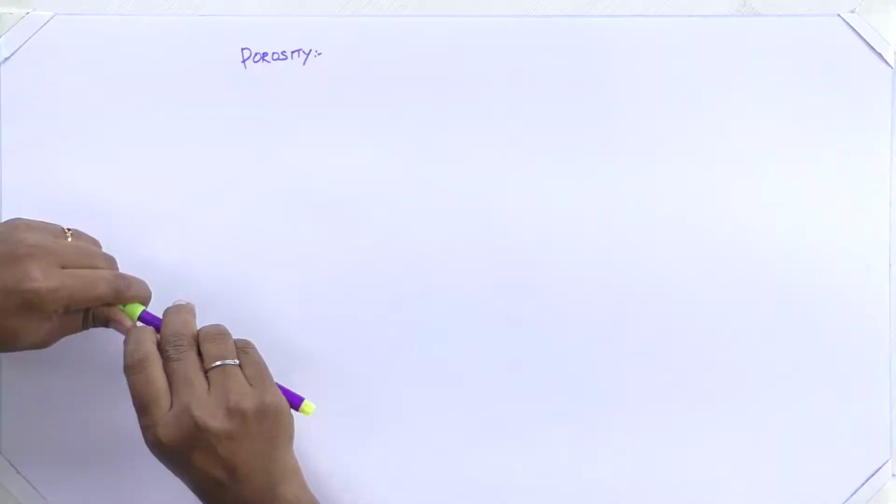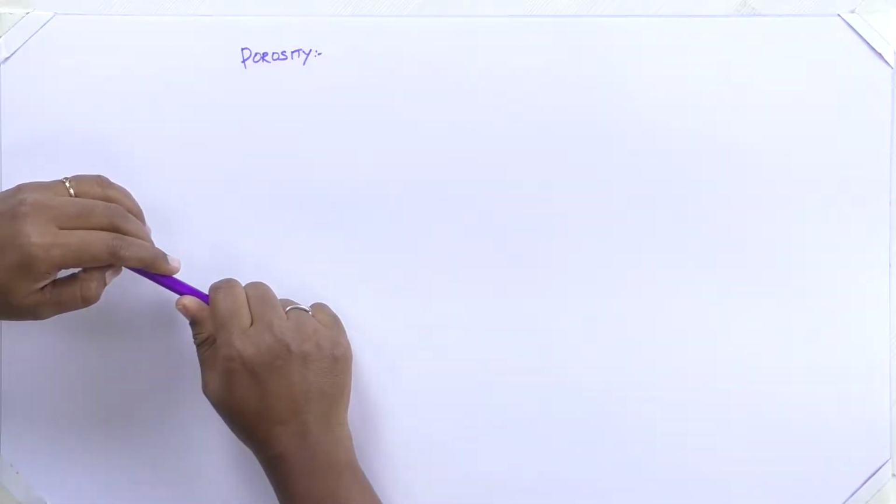In yesterday's lecture, we discussed aggregate size, shape and surface texture. Today, we are going to discuss packing density, how we can combine aggregates in a different manner to reduce the porosity, etc. In the last lecture, we saw that aggregate is an inert material and it forms the skeleton of the concrete, and it constitutes about 60 to 75% of the volume. All this we have discussed already.